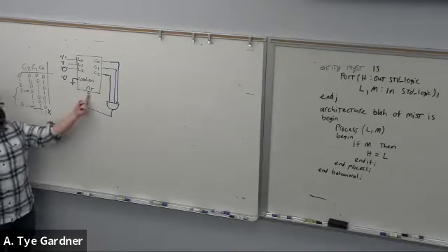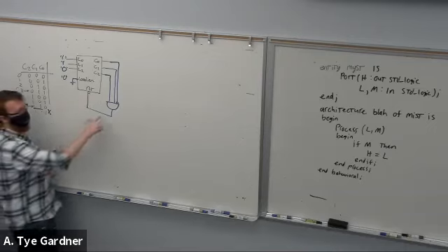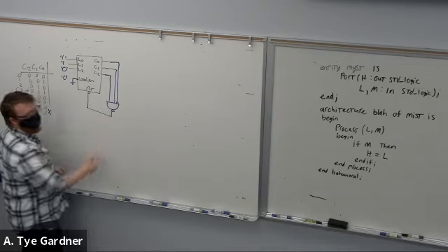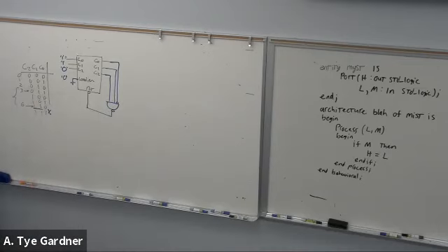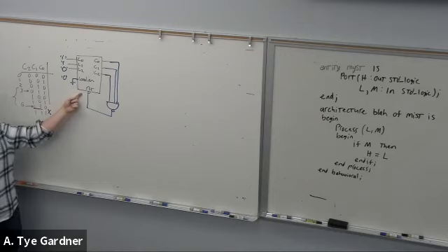Well, I have this bubble here for the active low reset, so I need that. But that would count 0 to 6. Okay, so it resets on 6. Is that correct? Yeah, so if I intended you to use the reset, I would say something about its reset condition, meaning is it synchronous or asynchronous?